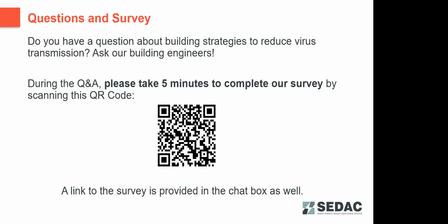And so having shovel-ready projects, getting in and finding out what you're lacking as far as difficulties moving airflow through a MERV 13, which really shouldn't be too difficult. That's telling me something else is a problem rather than the filter, because it's not a noticeable change to almost all blowers if there's not other things that need to be updated. In any case, there's a lot of money coming around, and as I mentioned in that webinar, this is a once in a generation type of opportunity for us to improve our schools.